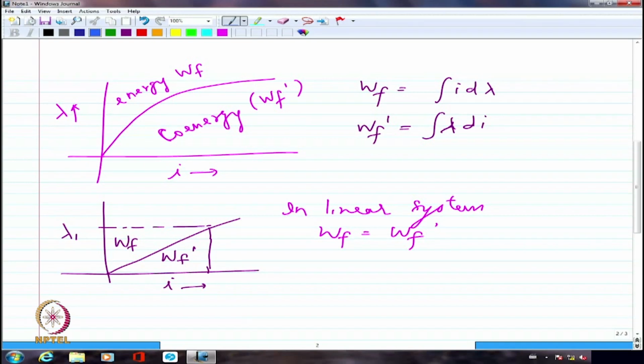I hope you understand. Because hysteresis will always talk about some amount of remnant flux density. So, if there is a remnant flux, the linearity is lost. When I is 0, the flux will not be 0 if there is a remnant flux. So, I can't say it's exactly a linear relationship. After that also, once saturation creeps in, if the I value is very large, at that point again it is non-linear. So, we are neglecting hysteresis when we are talking about this.